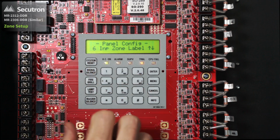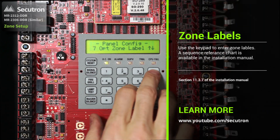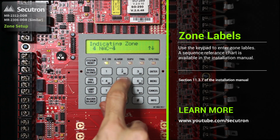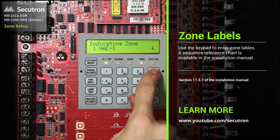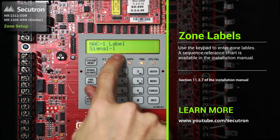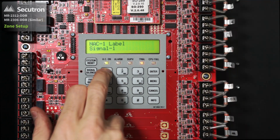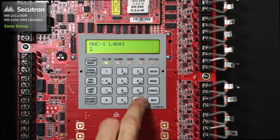The next option down in panel config is our output zone labels. So like our input zone labels, if we hit enter, we can see our NACs 1 through 4. And if we wanted to change the labeling on one of these NACs, we can select enter. We can see it's labeled as signal 1, but if we wanted to say change it to first floor signal, we'll hit the 1, cursor over,